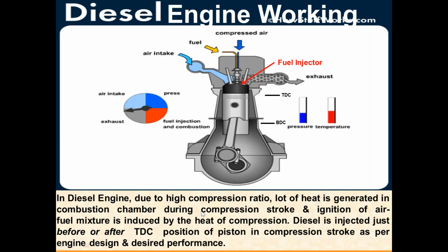In diesel engine, due to high compression ratio, a lot of heat is generated in the combustion chamber during compression stroke, and ignition of air fuel mixture is induced by heat of compression. This compression has very high heat, and that ignites the air fuel mixture. Diesel is injected just before or after TDC position of piston in compression stroke as per engine design and desired performance from the diesel engine, because this is adjustable.